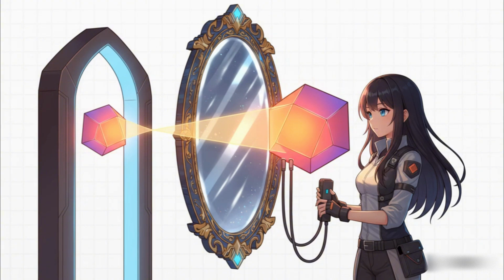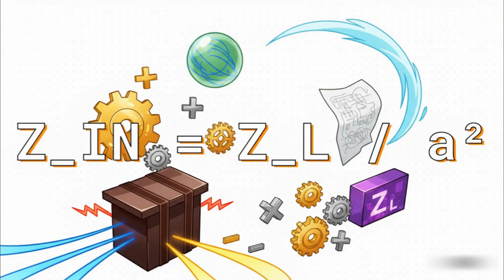And with our frequency domain goggles on, calculating this reflected impedance becomes incredibly simple. And here's the final magic trick. The input impedance that the source sees is just the load impedance, ZL, divided by the turns ratio squared. That's the entire calculation. A simple bit of algebra completely replaces some very complex magnetic field analysis.